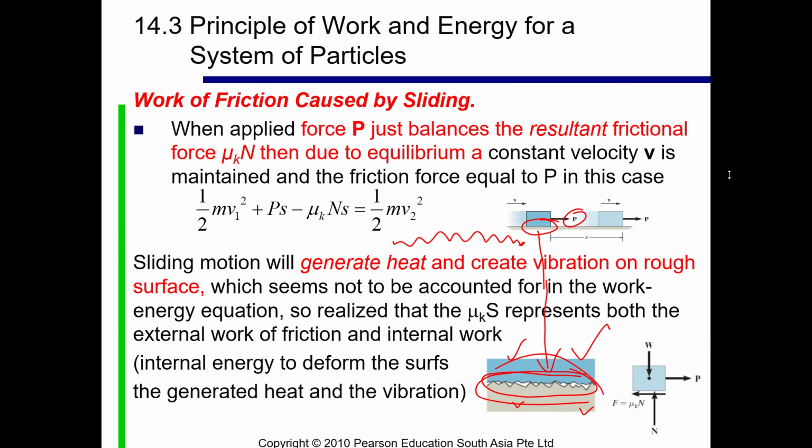There's going to be a force resisting the motion. That's true. If you look at the surfaces here, these peaks and valleys are kind of entangled with each other, right? When the object is at rest, we generally call it static friction, which says that these peaks and valleys are engaged with each other. When you try to apply force, there is a resistance towards the motion. Initially, it will not move unless you break a certain value of force of friction, and then it will start moving. That part where it is not moving is called static friction.